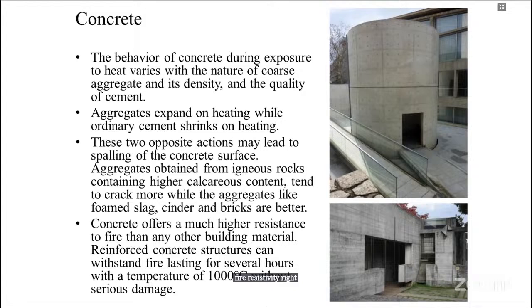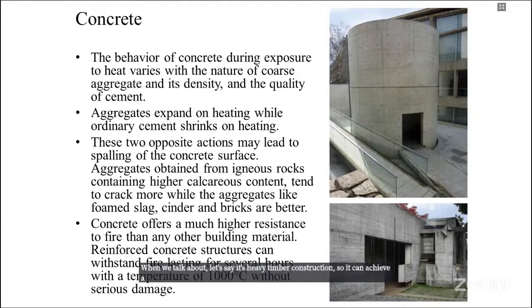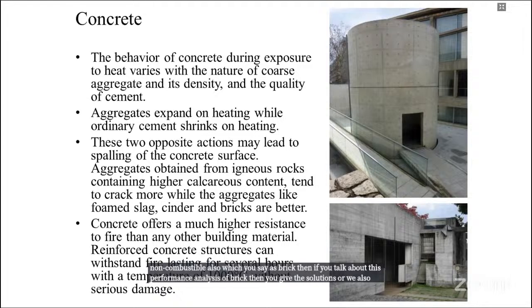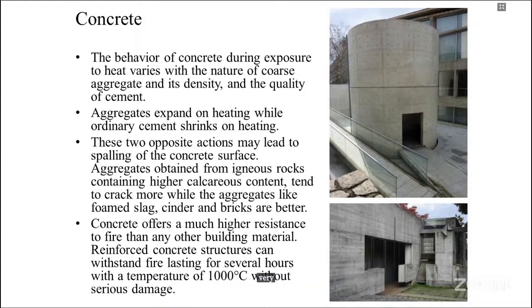When we talk about, let's say, heavy timber construction, it can achieve a 2-hour resistivity time lag. Why? Because of its mass, because it's heavy. When you are given a solution of a non-combustible material, say brick, and you look at the performance analysis of brick, we also advise that you have to make the thickness of the wall much more than the usual thickness. A 9-inch wall would not work to protect you from fire or something like that, right?